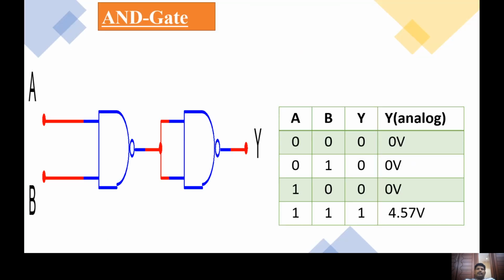Take another wire and connect it here. Now take one wire and connect this output to the logic output indicator. Depending upon the inputs you provide, you will get the outputs here. So you are implementing the NOT gate operation using a single NAND gate.